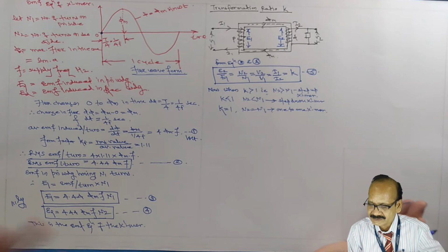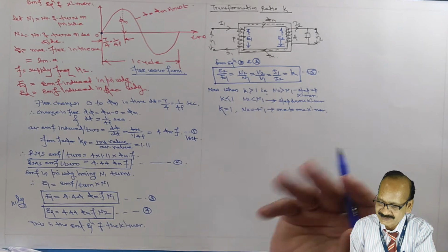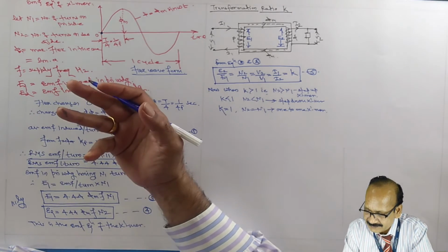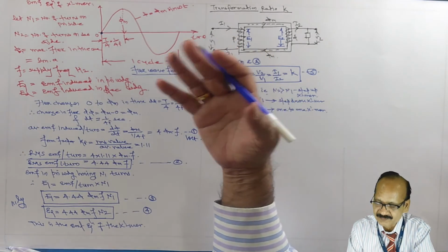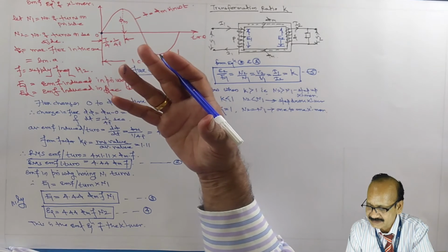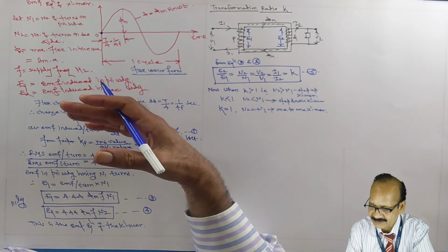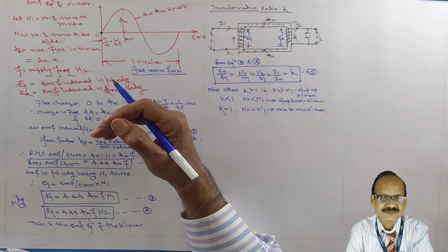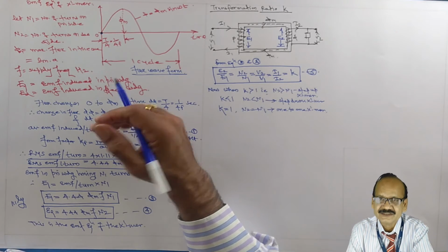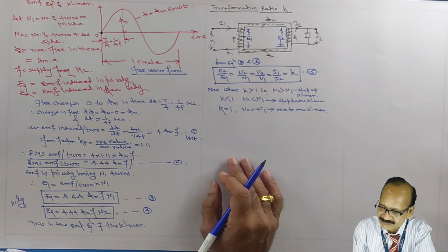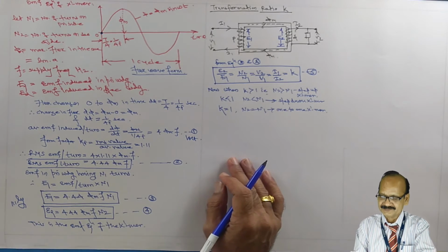Step up and step down transformers are used in the power system. Step up transformers transmit a large block of power over a long distance from the generating station to the load centers, whereas step down transformers are used at the consumer's end to reduce the voltage to the consumer's equipment level.